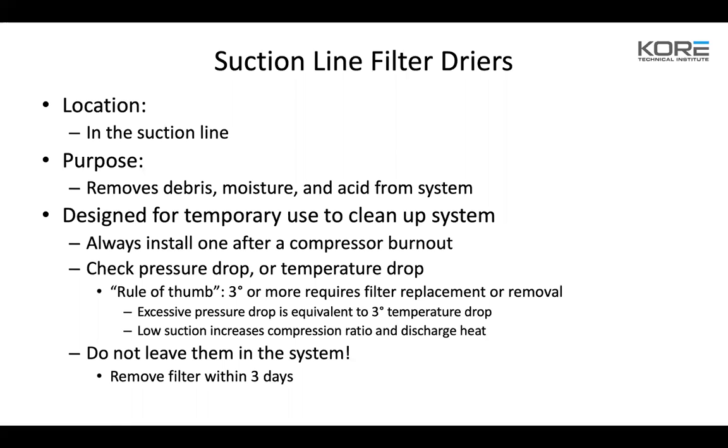Always install after a compressor burnout. Usually, on the sweat-in kind, there's going to be pressure taps on both sides. On the larger shell kind, you're going to take it off your suction king valve and the Schrader port on the suction filter itself. That'll be the difference between your pressure drop. So excessive pressure drop is equivalent to 3 degrees temperature drop. You're going to take that pressure drop and convert it to temperature. If you have 3 degrees, it's time to take those out. Usually they'll leave them in for a couple weeks on startup. That's usually in the scope of work, and then they'll pull those.